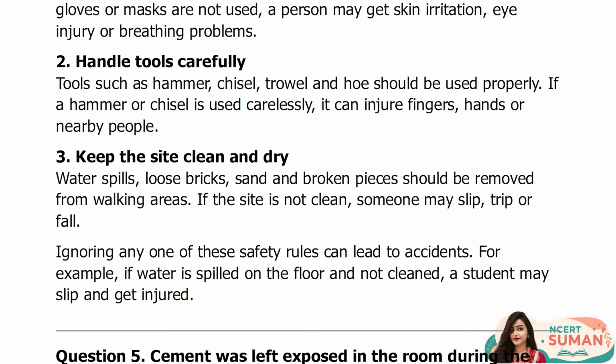Tools such as hammer, chisel, trowel, and hoe should be used properly. If a hammer or chisel is used carelessly, it can injure fingers, hands, or nearby people. 3. Keep the site clean and dry. Water spills, loose bricks, sand, and broken pieces should be removed from walking areas. If the site is not clean, someone may slip, trip, or fall. Ignoring any one of these safety rules can lead to accidents. For example, if water is spilled on the floor and not cleaned, a student may slip and get injured.